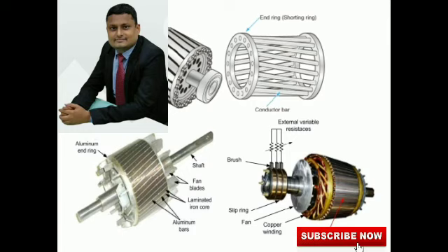Cross section of the rotor bar: AB equals IB by delta R. High current density means low area, more resistance, more starting torque, but more copper loss, and efficiency reduced. When the losses are more, the efficiency will get reduced. Since rotor is better cooled, higher delta than stator is allowed. So it must be 4 to 7 A per mm square. These are the conductor bars in the rotor.